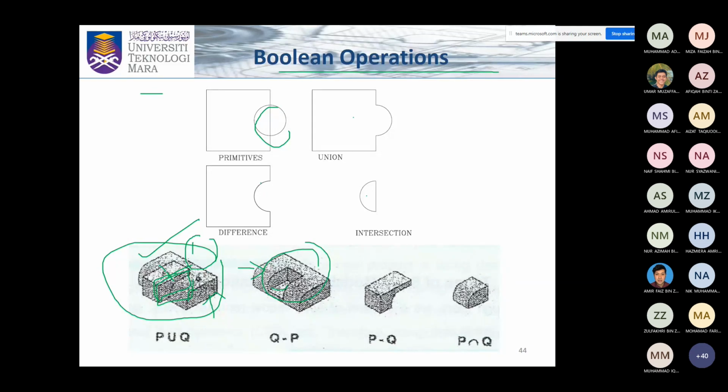In the usual CATIA you do, all of this is considered as one body. In Boolean operation, each extrusion added is actually a different body, so it will be recognized as different parts. It's not assembly, it's still design, but it's recognized as different parts.